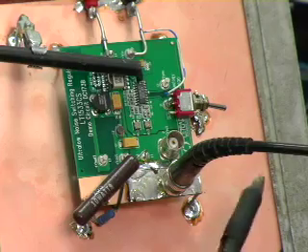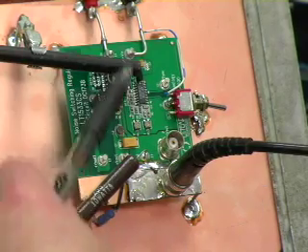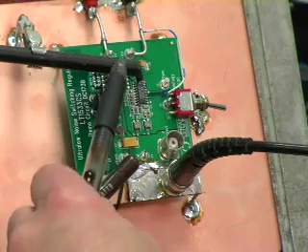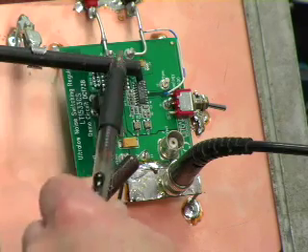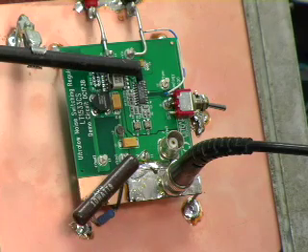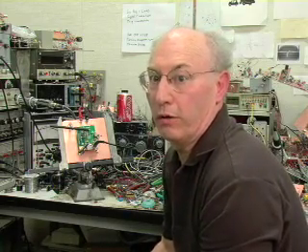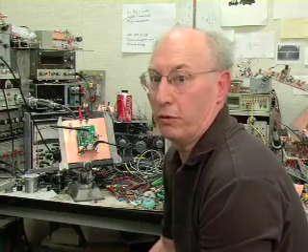Okay, we're here at the bench and we're actually going to measure some switching regulator noise. Let's take a look at what we've got for a setup. This is the actual switching regulator we're going to test. This big brown ugly resistor is the dummy load. This probe here is our floating, galvanically isolated trigger probe, which comes over here to the trigger channel of the oscilloscope. Before we actually measure noise, we want to determine what our signal path residual noise looks like.